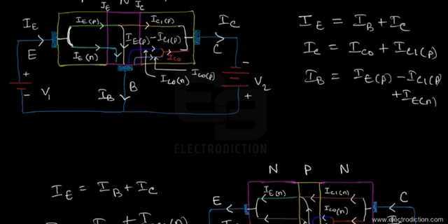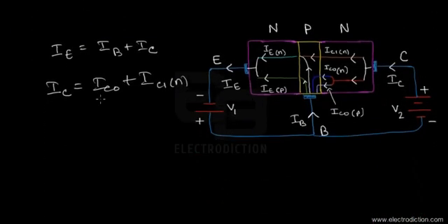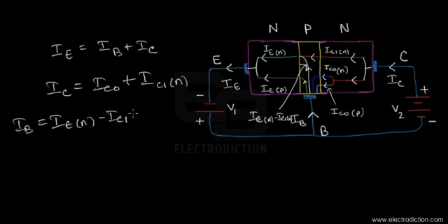Okay, that just makes the base current component for the PNP type transistor, and for the NPN type transistor, the base current component is obviously given by, sorry, I just forgot to name it over here. I'll just point them out. That is just given by IEN minus IC1N. It's a little cramped over here, so I'll just write it down clearly: that's IEN minus IC1N.